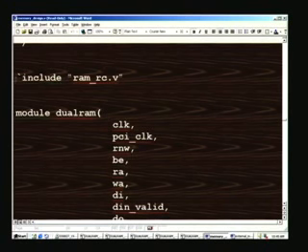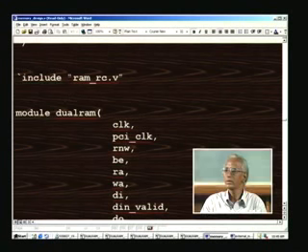Here we have to include another sub module. We have seen earlier the hierarchical approach by a flow chart, there will be a top module, the module that you see here, which is called dual RAM, an apt name, and this contains two RAMs. You have to access RAM 1 and RAM 2. This RAM will be in a different file as such, and that RAM must be included here. We have also said that the specialty here is row write and column access, and that is why I have labeled it like this. So it is basically a RAM.